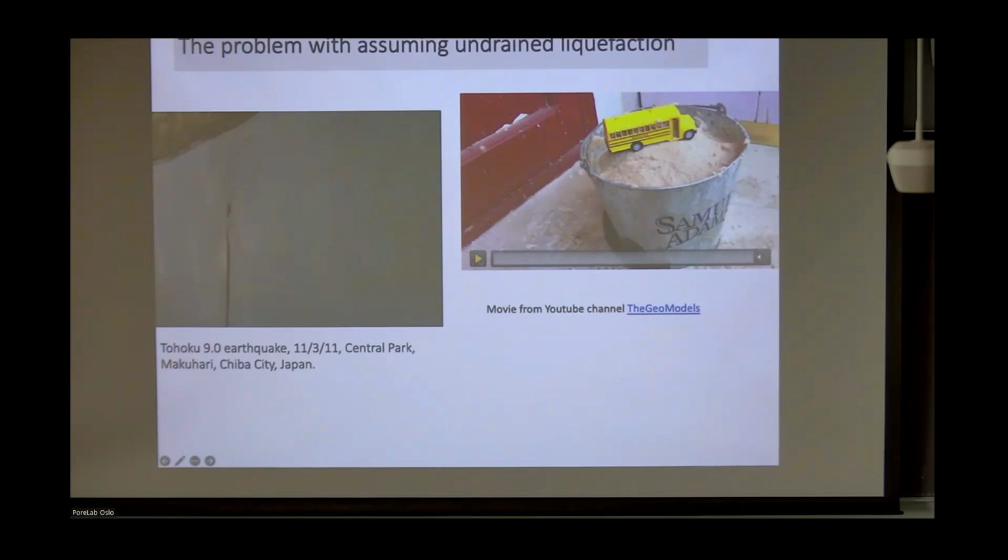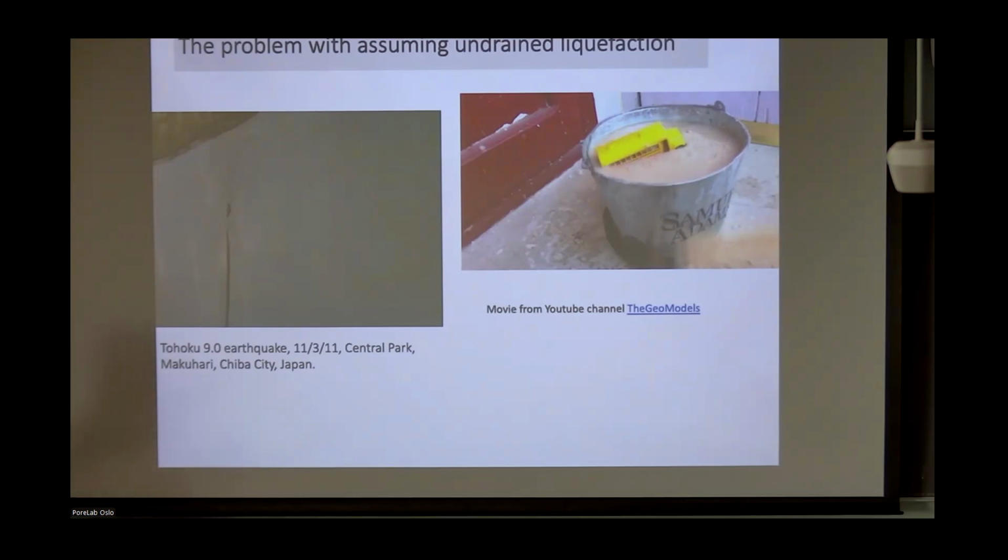Let me show you a demo that's shown to students to explain what is liquefaction. Here you see a bus sinking in sand that was filled with water, but you see that the water is coming out. It drained on the time scale of this process of shaking.